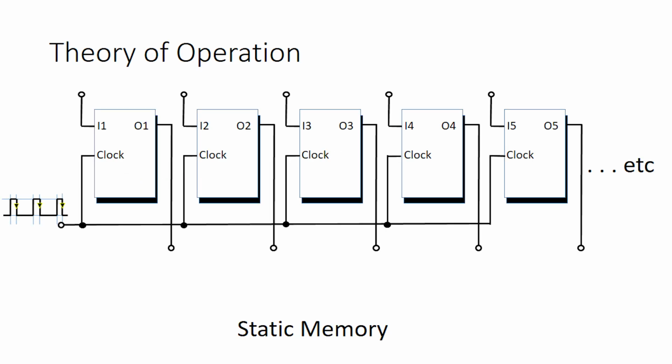So what they use them for mostly is this. That's a 5-bit static memory. So if I put 5 ones or zeros on the inputs there, then when the clock arrives, those 5 ones and zeros get transferred to the outputs. And that way you can hold a number, and it can keep that number through time, which the rest of combinational logic can't do.